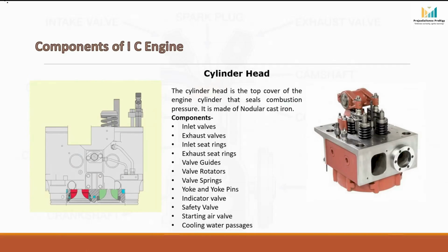Cooling water passages. The cylinder head contains internal passages which are known as cooling water passages. Cooling water continuously circulates through these passages and removes heat from critical areas like the flame plate, exhaust valve seats, injector surroundings, and the exhaust port region. This cooling is extremely important because the cylinder head is one of the hottest components of the engine. Without proper cooling, overheating can occur, which may lead to cracking, distortion, or gasket failure.